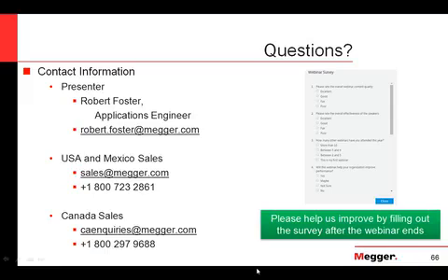They're at least doing the timing. And a lot of times the vacuum manufacturers, they'll give a spec where you can measure in the open position and in the closed position to get your total stroke length. I still think it's important, but a lot of times it's not always practical. And I always feel like manufacturers act like their breakers don't need to be tested at all. And of course, we make test equipment, and I was a field service engineer, so I believe testing is very important. But I would say it's still important, especially if you have circuit breakers that you've had failures on. There might be things you can pick up with travel that you won't see just in timing.